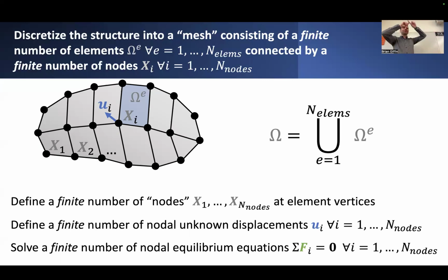If this were a simple grid in a two-dimensional domain, it'd be very simple to just discretize this into a bunch of smaller cubes and kind of treat the solution as being characteristic of variations of the solution within each one of those smaller cubes. Okay, so we've made the problem smaller. We've discretized our solid into a finite element mesh consisting of these elements and these discrete nodes.